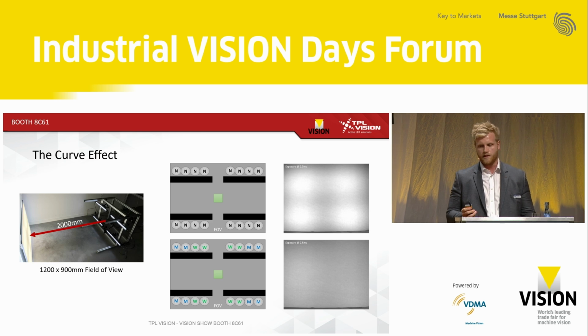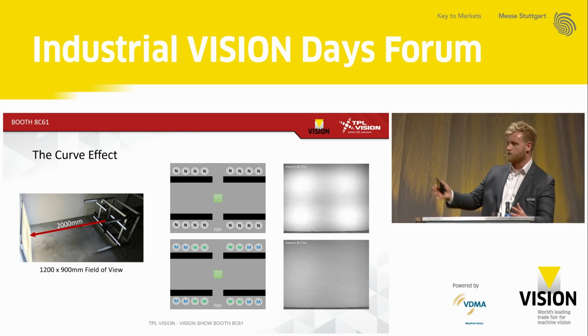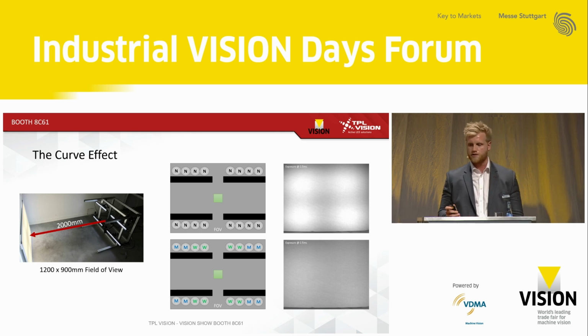They also do this on really large areas. So these are kind of simple applications. If you imagine you're inspecting a pallet or something like that, you can really play around with the different angle changers to get the best balance of uniformity and brightness. Because that's really what it's all about. You're sacrificing some brightness to achieve higher uniformity, and it's really about finding that balance. You can't just have really powerful lights, otherwise you'll see these hot spots.